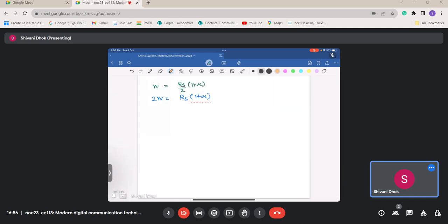4800 bits per second, and the constellation that we are using is 16 QAM. So bit rate is given as 4800 bits per second, and the constellation is M-QAM with M equal to 16, which means that k, the number of bits, is log M to the base 2, which is log 16 to the base 2, which comes out to be 4.